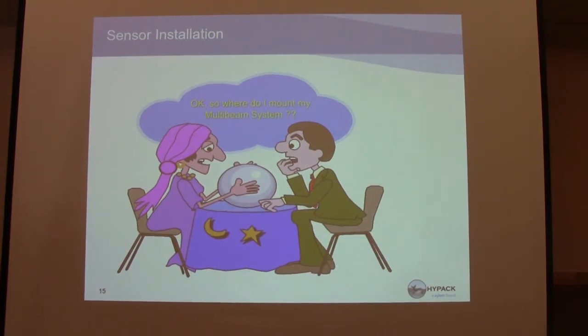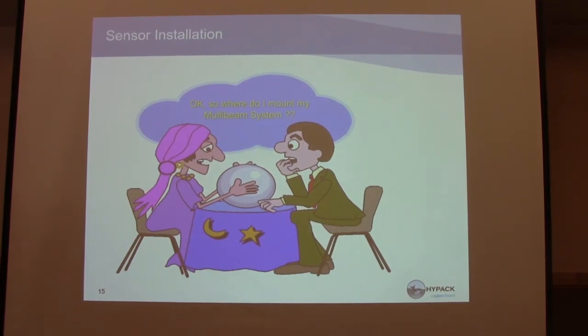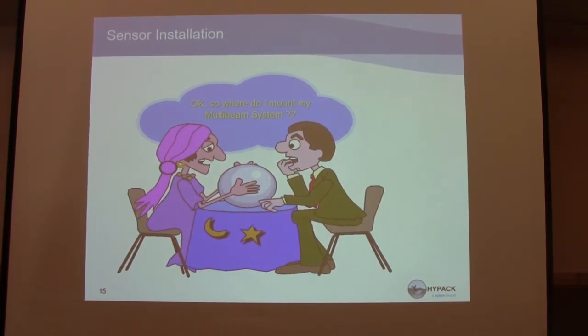Okay? Because the way that multibeam works is it's got a transmitter and receiver and it's expecting the stuff to go out at a certain time in a position and to receive it back so that it can map out the slant range and angle to get a good position of the sound. Well, if that vibrates, things are out a centimeter or 2 centimeters, that throws the whole thing out. So you're going to see artifacts in your data.